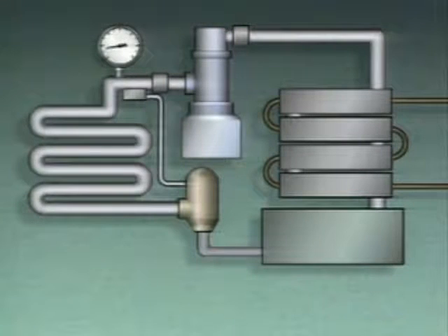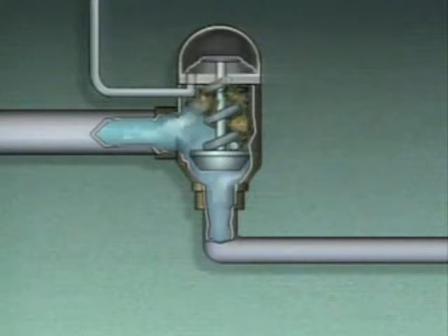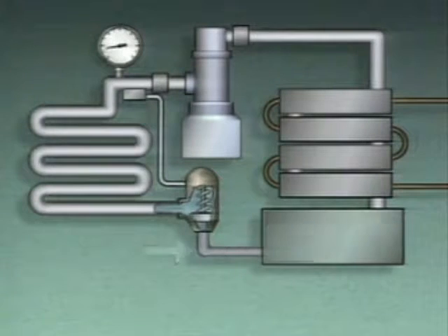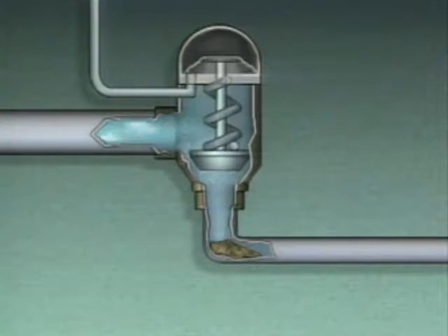One possible cause of reduced flow through the evaporator is a stuck expansion valve. Dirt or scale can obstruct the valve and prevent it from opening properly. The same result can occur if there is a blockage between the receiver and the expansion valve. The blockage acts like another expansion valve, so the refrigerant will be cooler downstream from the blockage. One way to check for a blockage is to feel the line for cold spots.